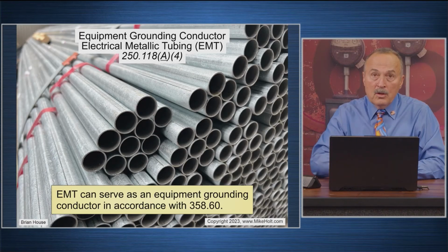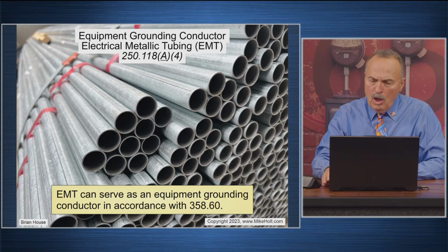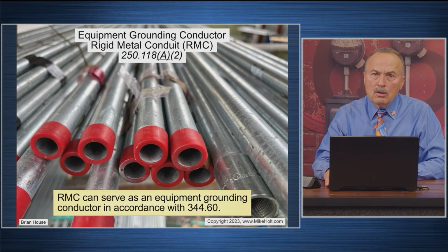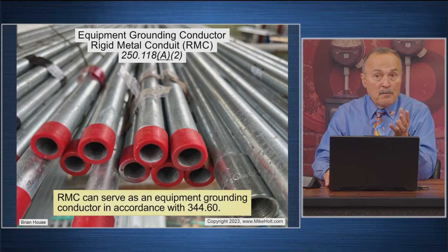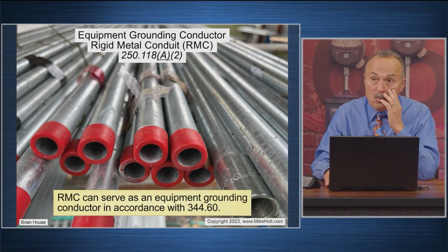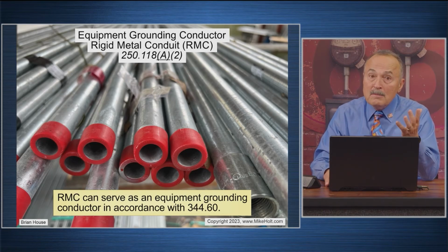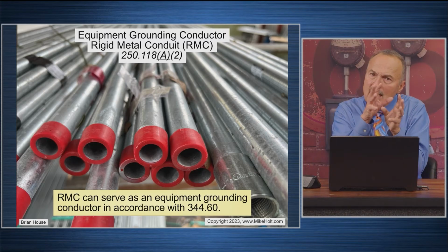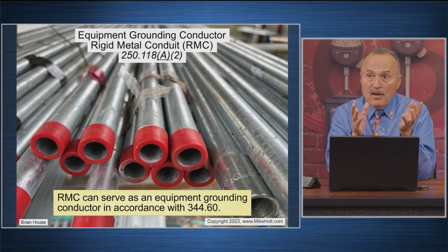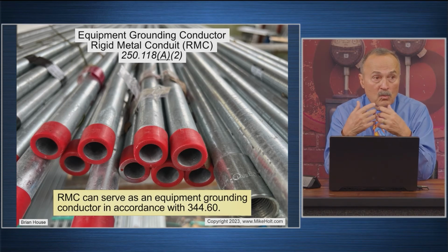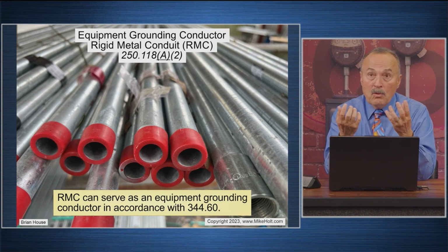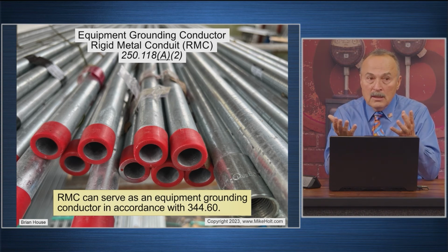So there are people out there that do not like the metal raceway to serve as the equipment ground. Well, I'm okay with rigid, EMT, no. But I can understand, because there are industries out there that these guys might be working in, that have forklifts, they have equipment, and there's damage to rigid metal conduit. So those guys that are working in that world, all their life, they've always put an equipment grounding conductor inside of a metal raceway because they're always spec'd out. I mean, that's the world they've worked from. They just can't imagine that. Of course, they couldn't even conceive the concept of running Romex, much less in Chicago.